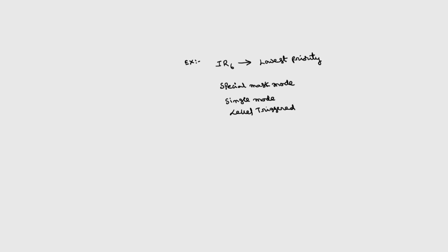These are the specifications that I want to use, and I have to program this 8259. Non-specific fully nested, then specific EOI mode.